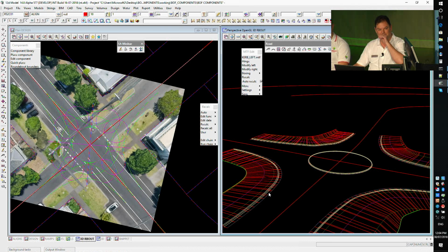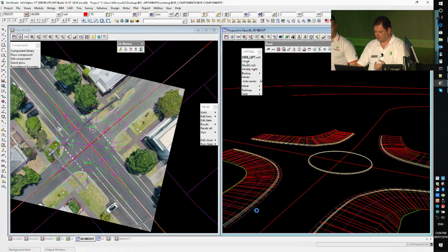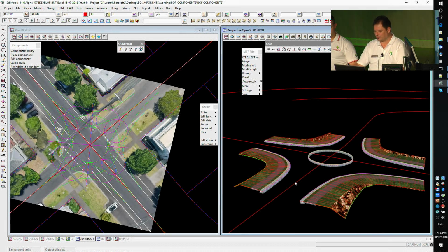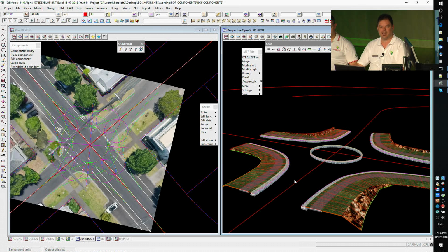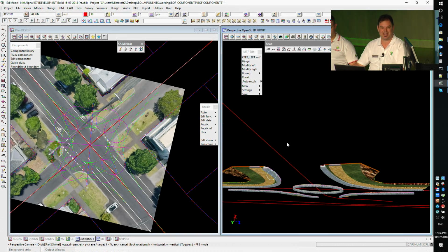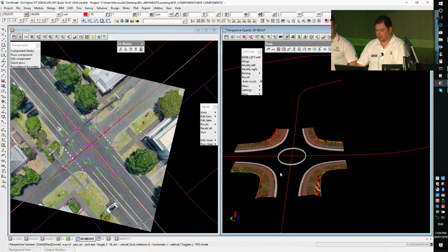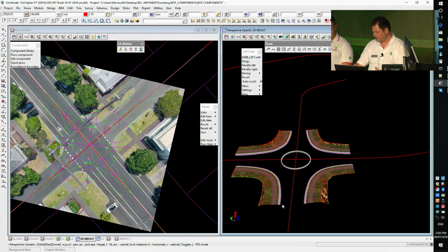And what's really good now is I've created the meshes as well. So just add these meshes in. So there's the meshes in there, all the solid objects. I could go and take a look at underneath it as well, that all the meshes have been created. I can see the bedding sand and things for the pavement. The next thing though, which Peter briefly touched on yesterday, was this area here in my intersection that I can't really solve with MTF.